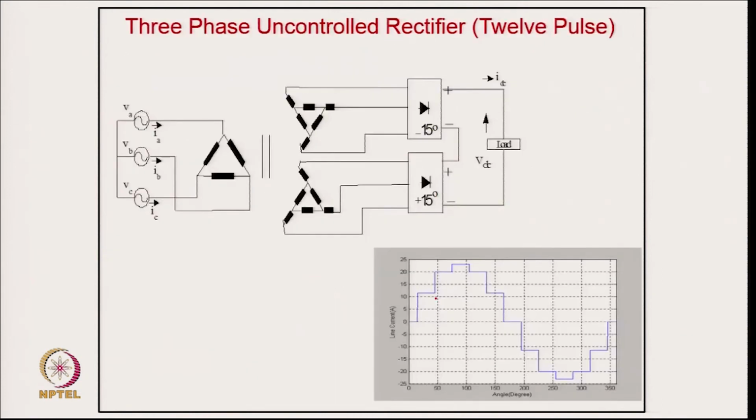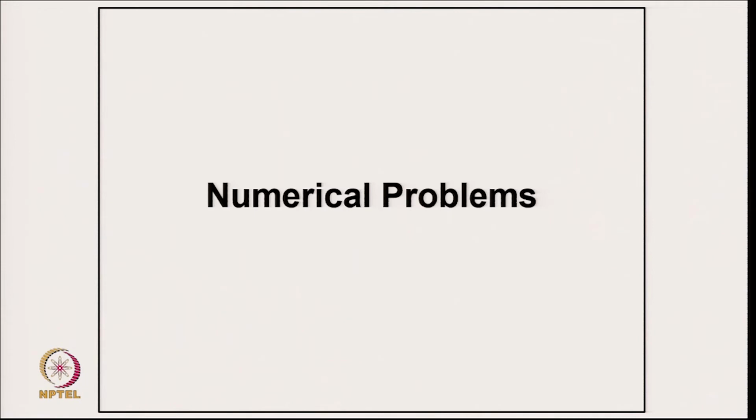So you have the supply current here, and because of the 12 pulse you will not get harmonics lower than the 11th, and the current will be closer to a sine wave, but still you have around 15 to 16% total harmonic distortion of this current.